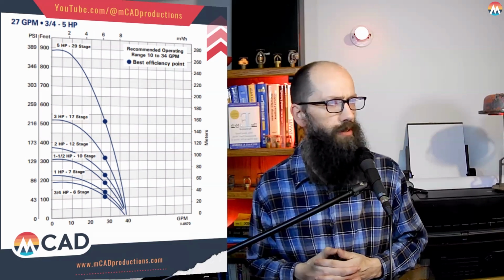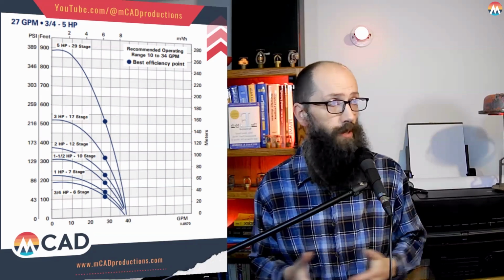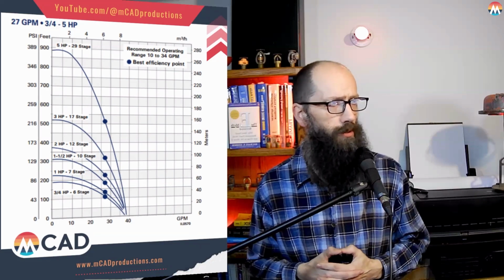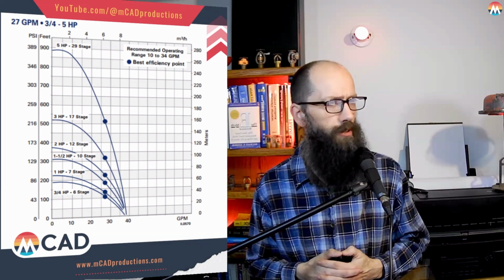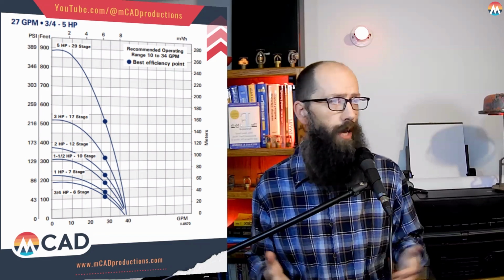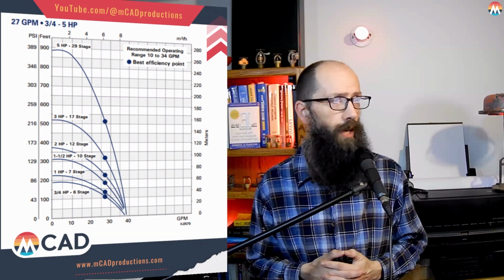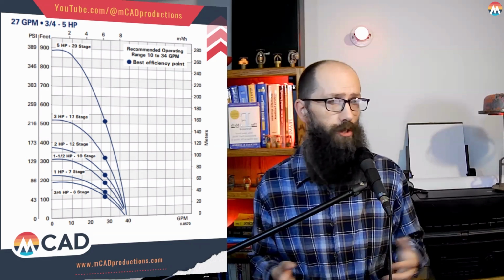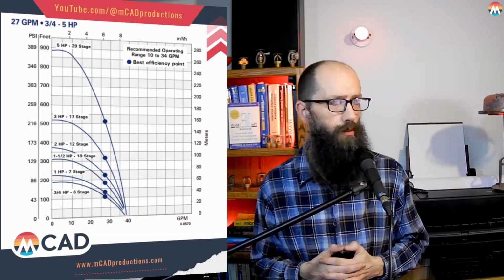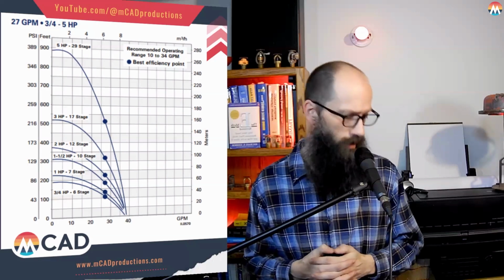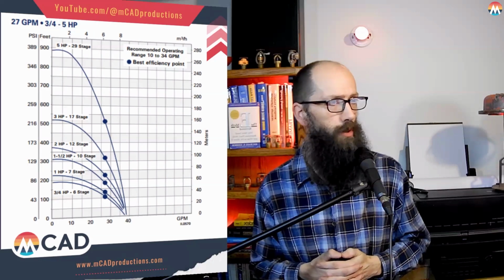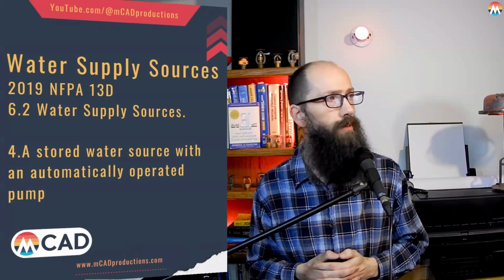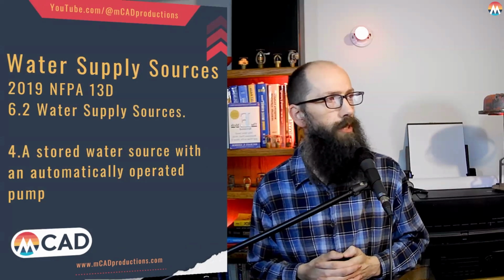I think they usually use like a 2-horse, but that's designed to work at almost, this looks like, 375 feet down. And so when we put it at 0 head pressure, where it doesn't have to suck up the water from underneath the ground, it just works tremendously well.